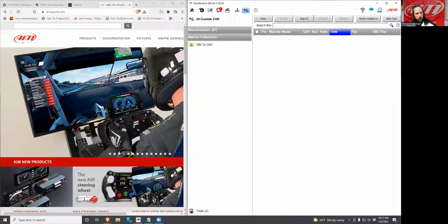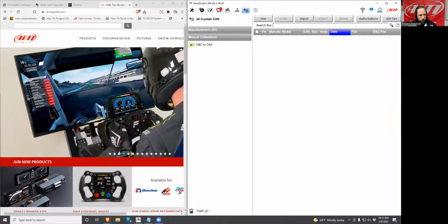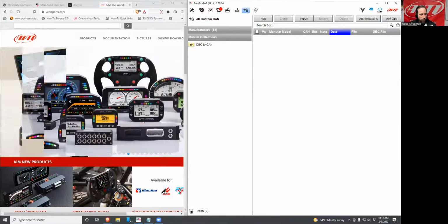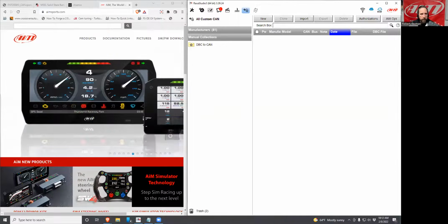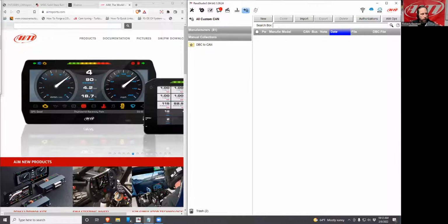So to do this, we want to make sure that we have the right keypad. To match our configuration interface, it needs to be a CANopen keypad. It needs to have the matching bus speed, and it needs to have the correct node ID.